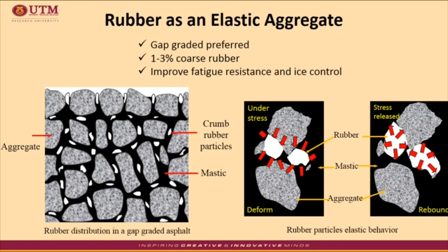By limiting the reaction time between asphalt binder and the rubber particles, and to be exact, using a coarse granulated rubber with low surface area, the rubber particles are able to retain their physical shape and rigidity. In a gap-graded mixture, the gaps provided between the fine and coarse aggregate are allocated to the rubber particles within the mixture. On the other hand, in a densely graded mixture, the aggregate gradation must be on the coarser side of the specification to allow for rubber modification.